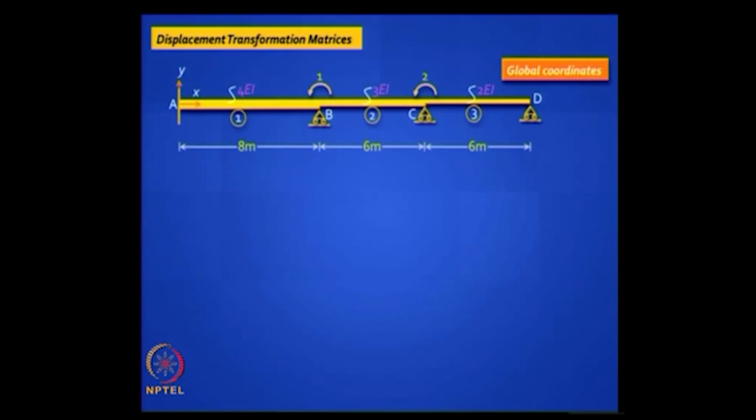Leave it in peace. Don't put a curled arrow there and give it a number, because we are not interested in that rotation. We don't want to know theta D, because we know the bending moment at D is, in this case, 50 kilonewton meter. We will bring all that later, but the first step, if you want to work with reduced kinematic indeterminacy, is don't include that as an active degree of freedom.